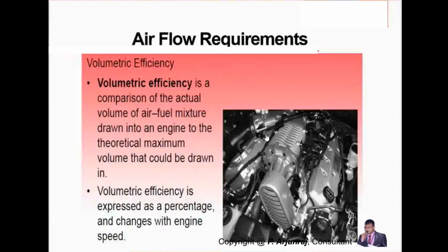Normally the volumetric efficiency is expressed as a percentage, and it will also vary with respect to the engine speed. The volumetric efficiency is not going to be constant. It increases with engine speed. At idle RPM, the efficiency will be lesser. The turbocharger helps to increase volumetric efficiency, because when the engine is running at idle or low RPM, the air going into the engine will be lesser. So the airflow requirement gets matched with the help of external devices like the turbocharger.